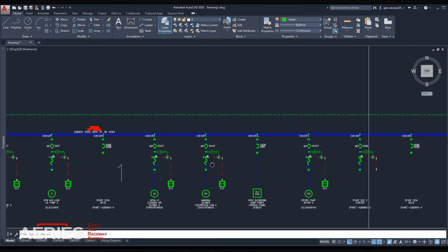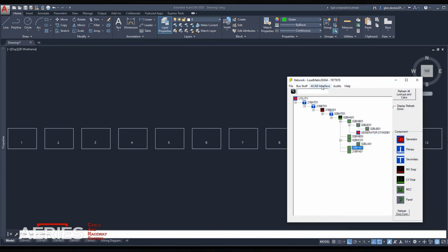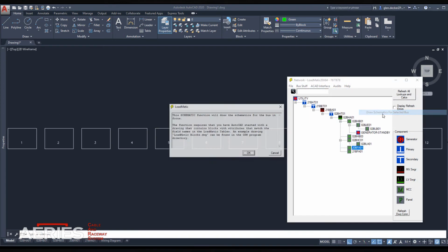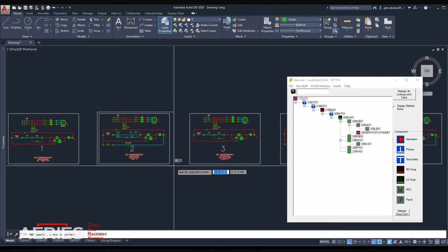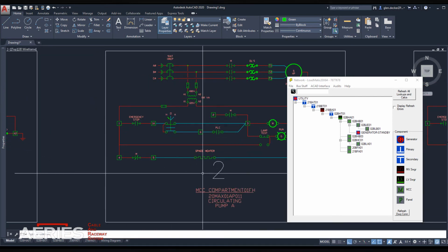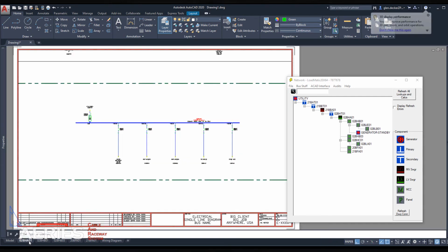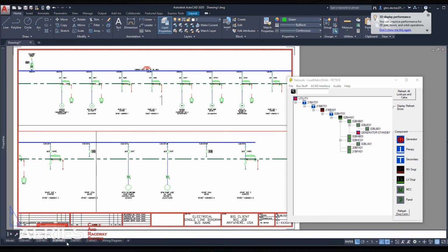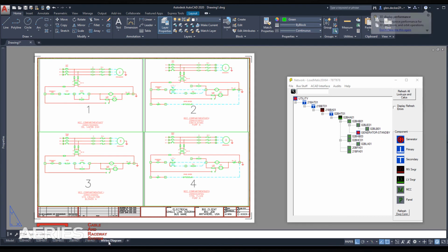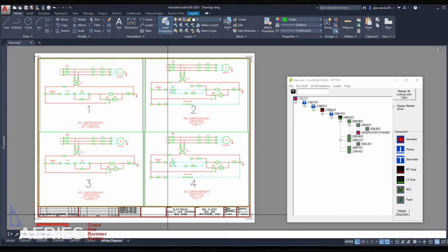Motor control schematics are also created automatically. Open an AutoCAD file with a schematic template and then select Draw. Layout tabs with title blocks and viewports allow the deliverables to be drawn and updated quickly, printed, and issued. Information is entered once and used repeatedly on reports and drawings to ensure a consistent deliverable package.